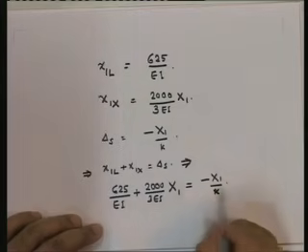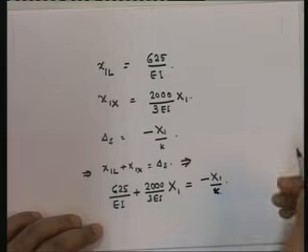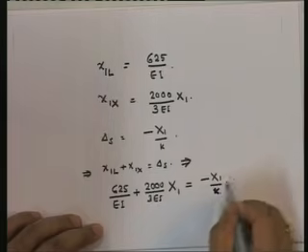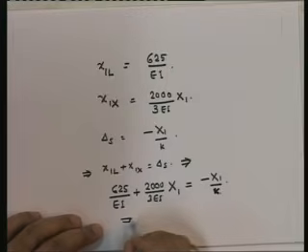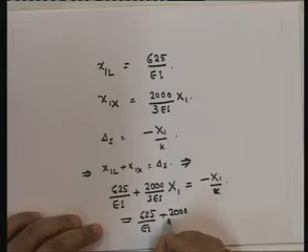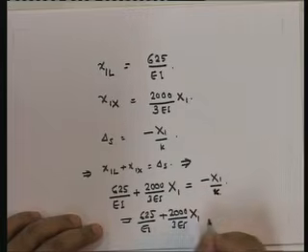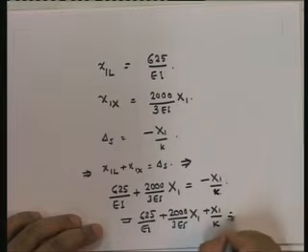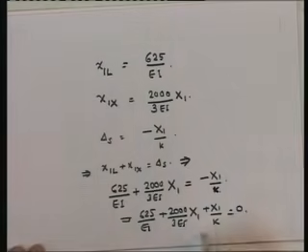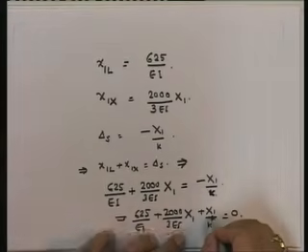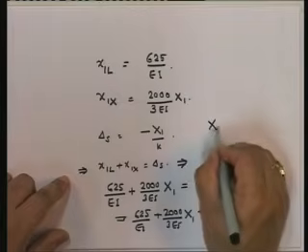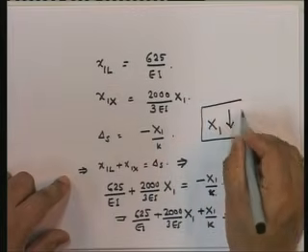Okay, and if you look at this, k is a known factor because it's a spring constant. We know the flexibility. So therefore we can find out x1 directly, because this will become nothing but 625 upon EI plus 2000 upon 3 EI into x1 plus x1 by k is equal to 0, and this you can solve for x1. Note that because of the foundation flexibility, the value of x1 changes. If you look at this, the value of x1 actually goes down due to the foundation flexibility.